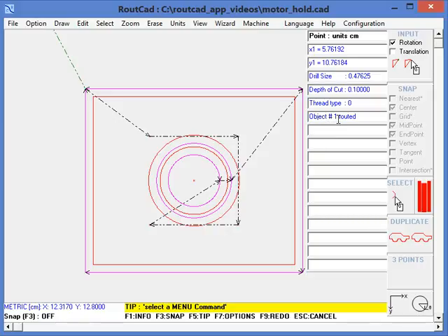First of all, this point is the first object to be routed, and it's only 0.1 centimeter deep. The reason why we made this point is basically a marker that only goes 0.1 centimeter deep in the material to give us a physical cue as to where the machining will start on this part. Now, after it goes to the first point, the CNC machine will move up in the air by the offset clearance to material distance that we have defined in the configuration and go to the next point to be machined.